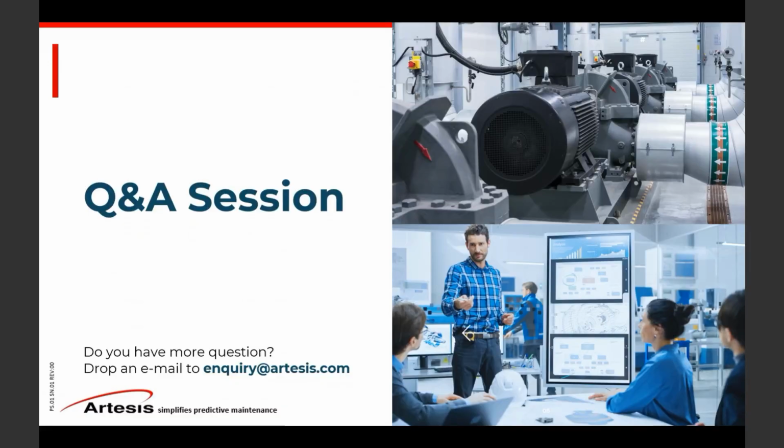There's another question: which technology inputs is your software working on? Only vibration analysis or anything else? I thought I pretty much covered this already. We don't use vibration. Our system is sensorless. We're using only electrical signals, voltage and current, and we turn the motor itself into a sensor where it gives you all your vibration information, or electrical and process and pump performance monitoring. So that's why at the end, I mentioned the beauty of our system is that it's capable of capturing all this information from different disciplines, which you would normally use different tools to detect.